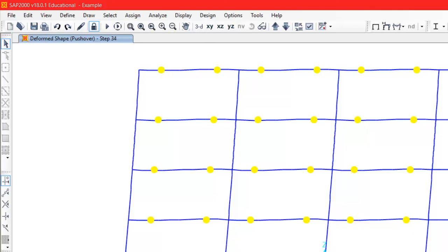The one we already saw is already taking into consideration all of the shear force at the base. And of course, you need to normalize. The pushover curve that we have shown is in kips. You need to divide it by the seismic weight. So it will be something like 0.2 or so on.